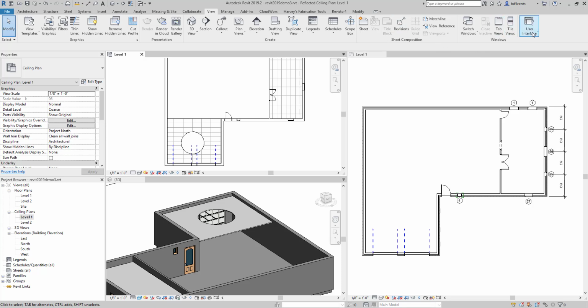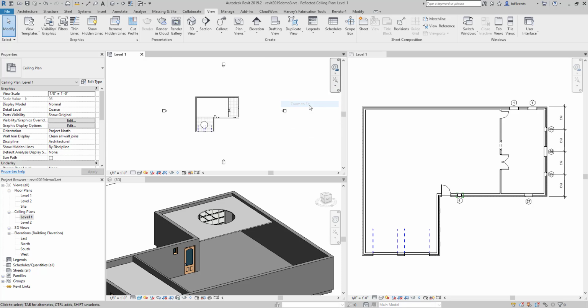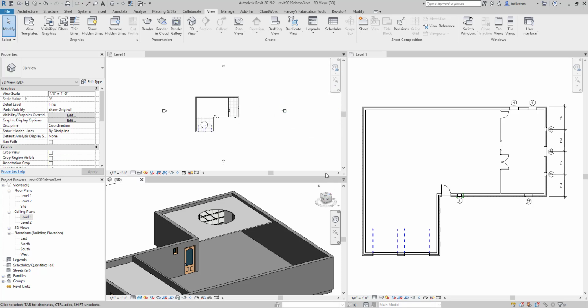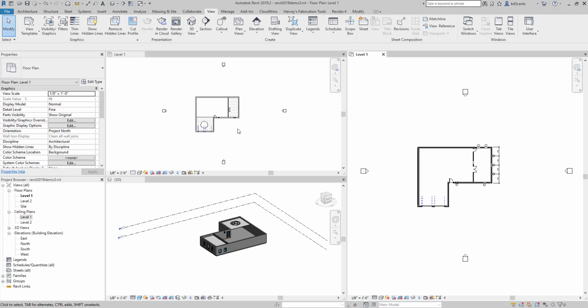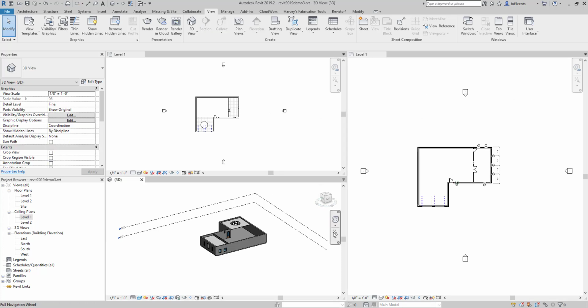I've got to try to find it real quick, so bear with me. Oh, we're going to view it from here. So we're going to zoom all to fit, or zoom to fit that particular view. And then we can actually come into each view and hit ZE. That's going to get it to zoom extents. So just know that that's there.